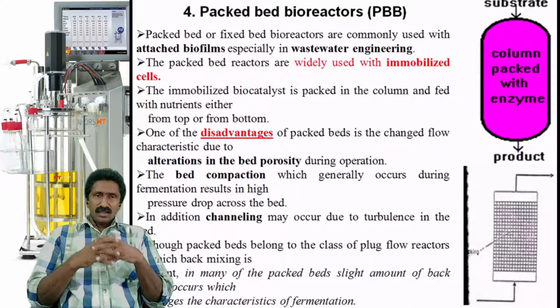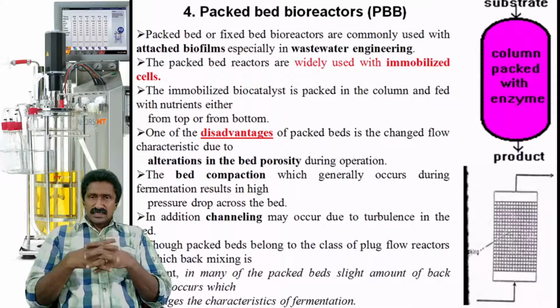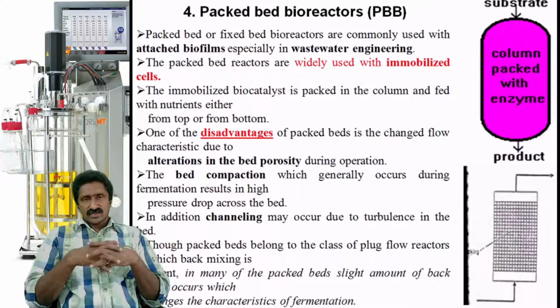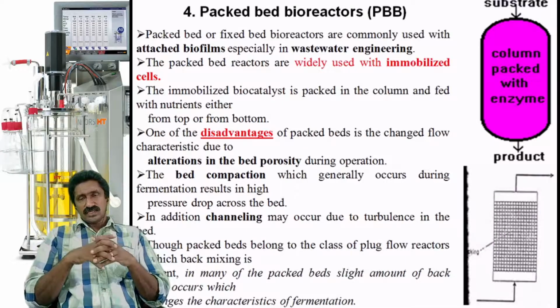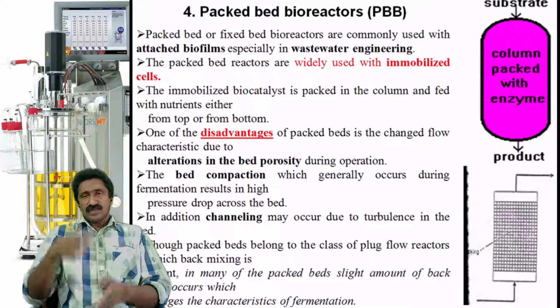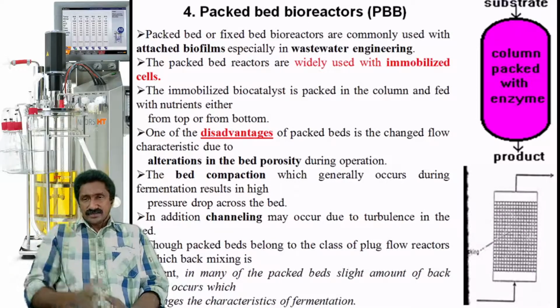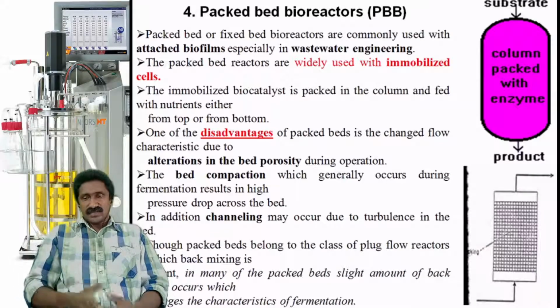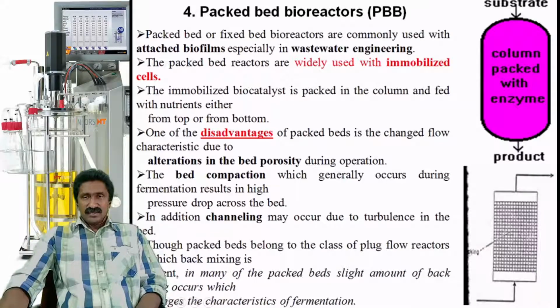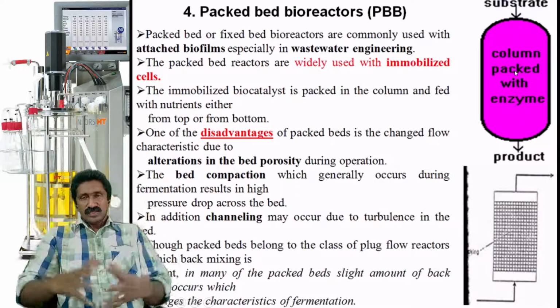One of the disadvantages of packed beds is the changed flow characteristics due to alterations in the bed porosity during operation. Since it's a packed bed, sometimes there is a localized formation of channels during the flow, which results in channeling of the entire contents through that channel. For example, imagine a crack created in between, and the medium flows through it instead of flowing uniformly through the entire bed.